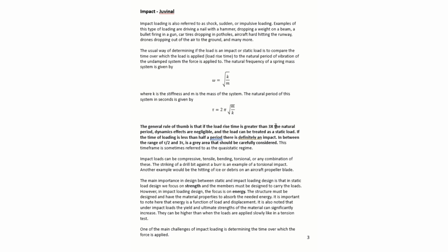And again, if that's 3 times the natural period, it can be treated as a fully static load. If the time of loading is less than half a period, then it's definitely an impact. And the region that becomes a little gray is between half a period and 3 periods. And we often call that a quasi-static regime. And in that case, you would want to look at both situations.